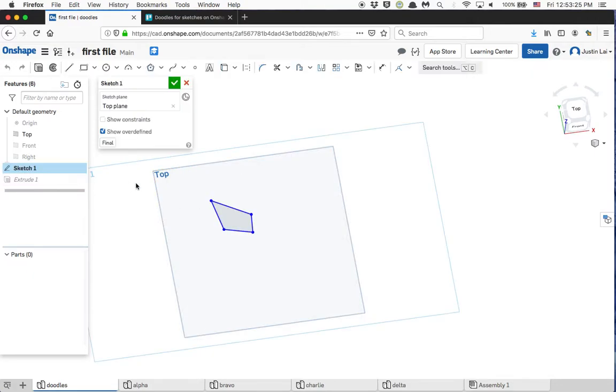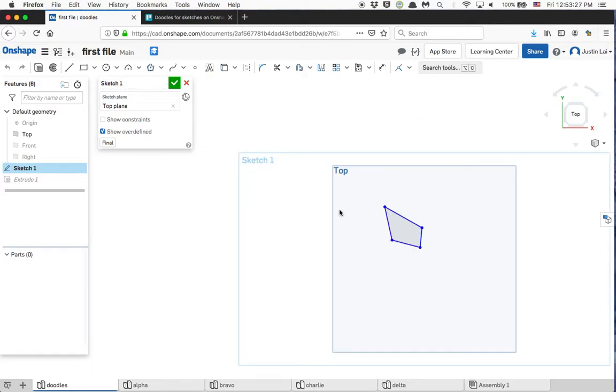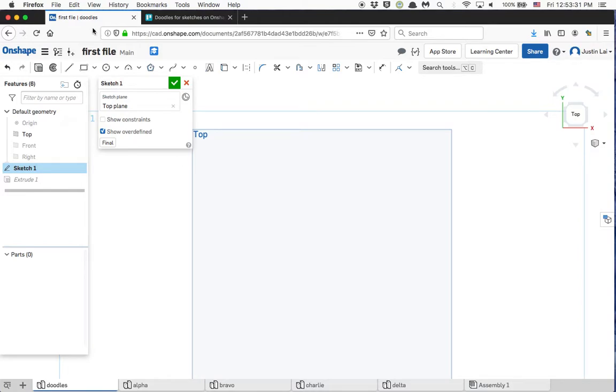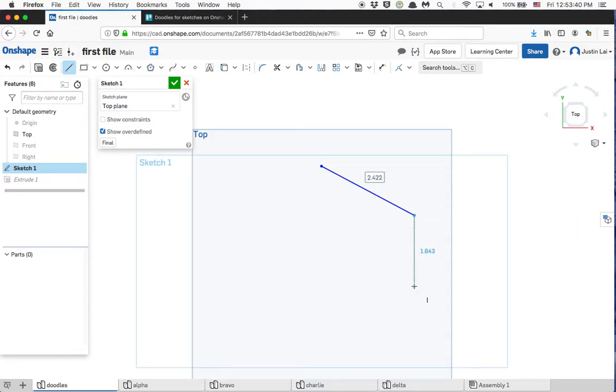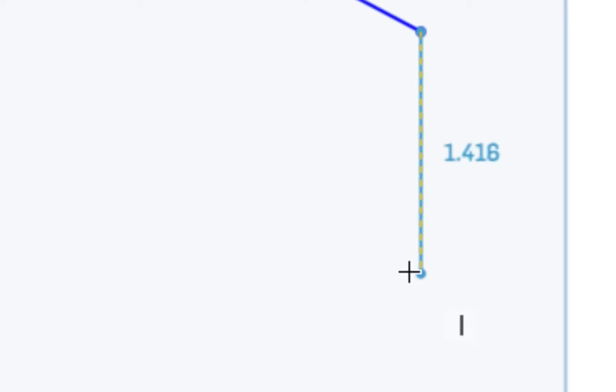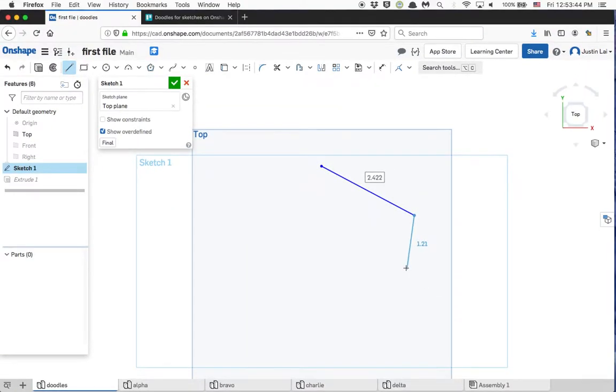Now, let's actually do it the other way around. And just for practice, we're just going to delete everything. So we can use our selection rectangle, delete. And let's just build it up with our line tool, the letter L, and just put 4 arbitrary points. You'll notice that if you want to go vertical, Onshape's going to be like, hey, you want to be vertical? And right now we don't want that help. So hold the shift key on your keyboard. I'm just going to do a 4-sided figure, and try not to have any parallel sides or anything like that.